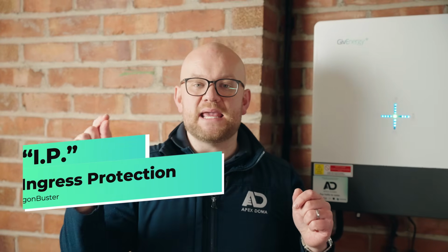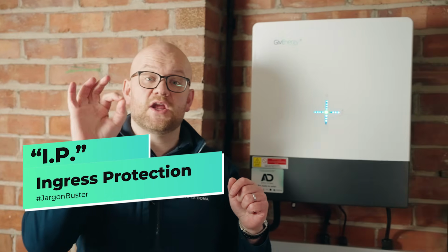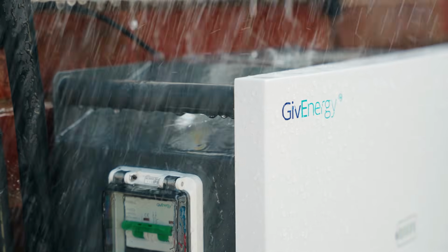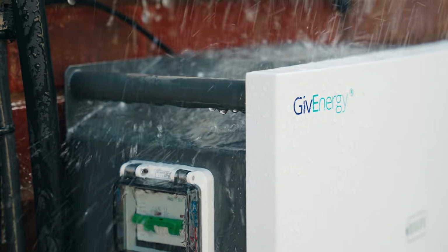When it comes to installing an inverter and battery outside, not all inverters and batteries can go outside. You want to have a look at the data sheet and look for a thing called an IP rating. This stands for ingress protection. This is a protection against dust and against water. If the IP rating is high enough, for example, these have quite a nice high IP rating, then they can be stored outside the property.